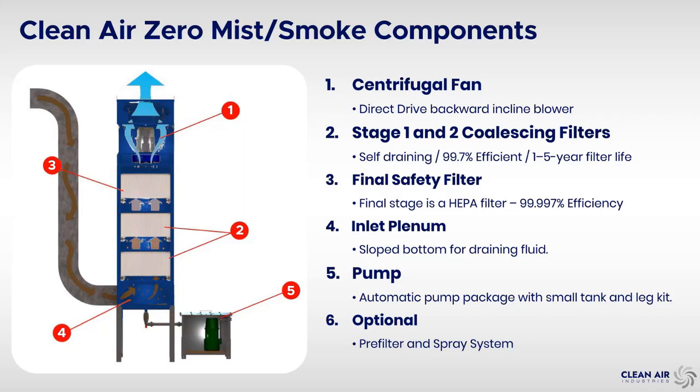The last thing you want to do in these type of collectors is have any kind of drying out of that filter. It'll block them pretty quickly if you dry them out. So if you're doing wire drawing or some kind of a dry-ish type application, then we recommend the spray system under there, and they work really, really well in those situations.